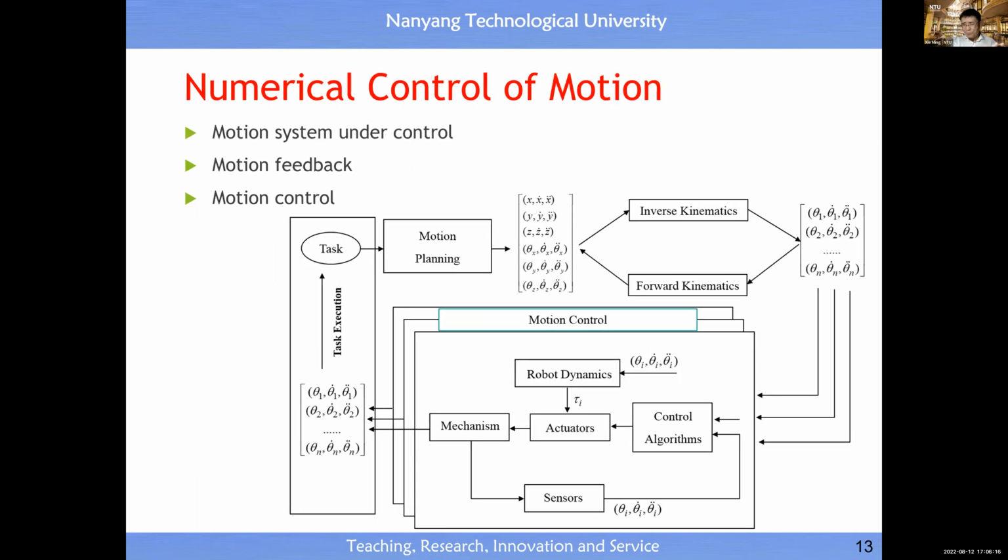Right? And in robotics, there is wide use of digital sensors for the measurement of joint angle and joint velocity, because we need to measure, you see, theta one dot. Theta one dot means velocity of theta one, all right? Then theta two, theta n, because a robotic arm may have n degrees of freedom, right? So then you need to have n such sensors to measure all this velocity. So you see, this lecture is very, very relevant to the study of robotics, right?